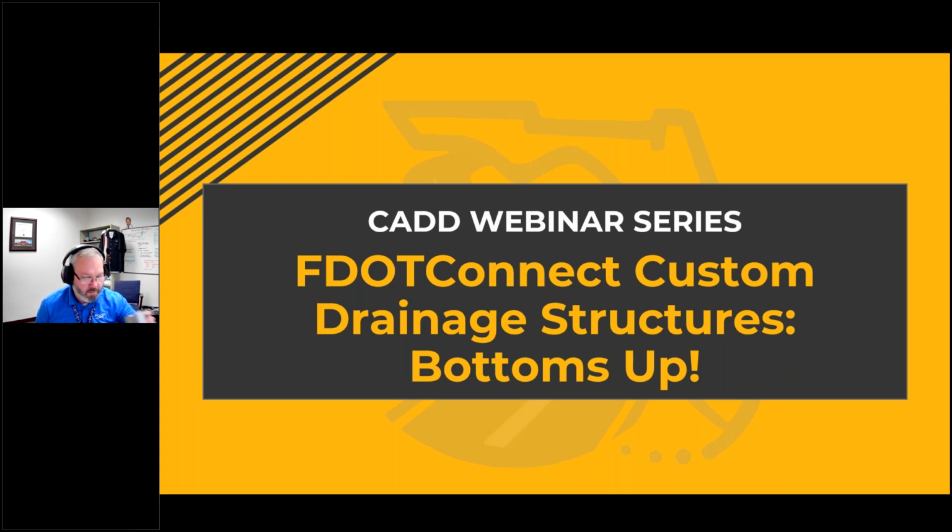Adding sump in there, the way they were originally done, the elevation point that located the incoming and outgoing inverts in the bottom of the bottom cell was actually placed directly on the surface of the bottom of the box, which is not exactly correct.